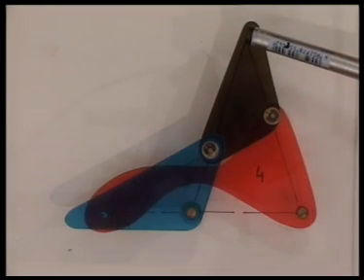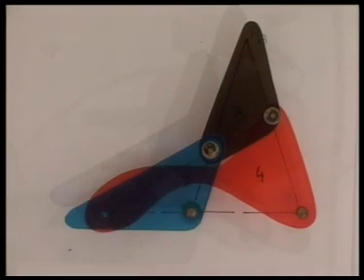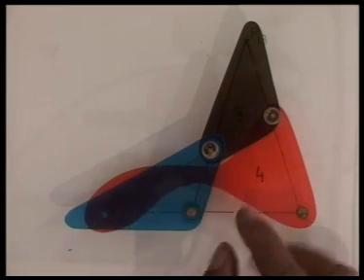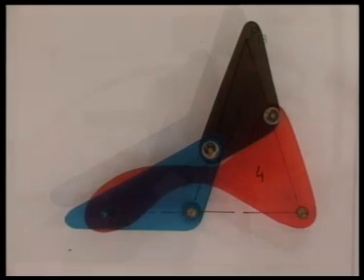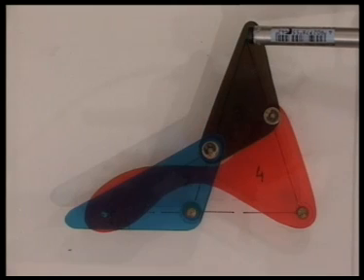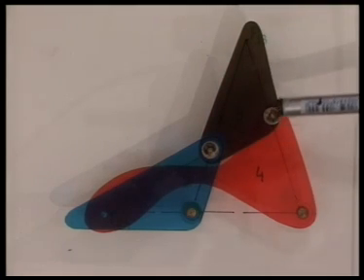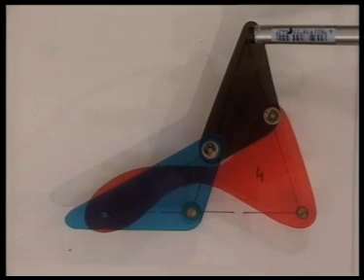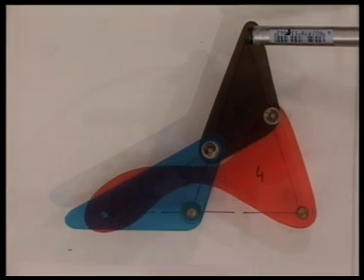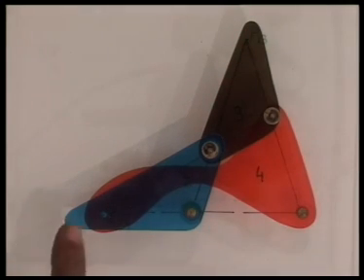So this is 1, 3 and this is 2, 4. Now if we move this linkage around this configuration, because this point is P1, 3, that means the link 3 is instantaneously rotating about this point, which does not move. This point has 0 velocity, as we will see when we move this linkage.